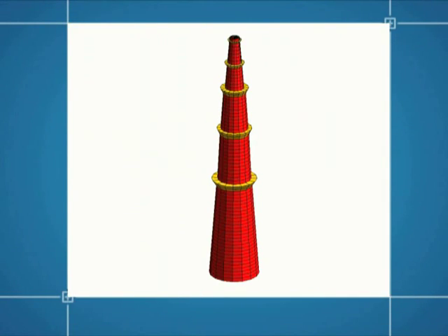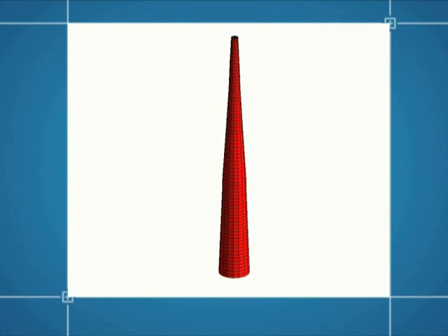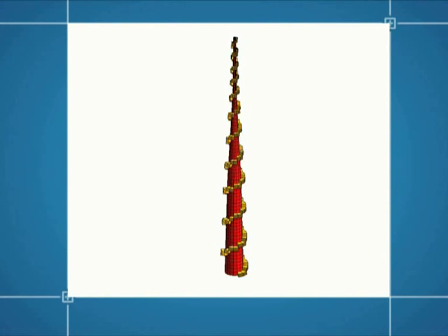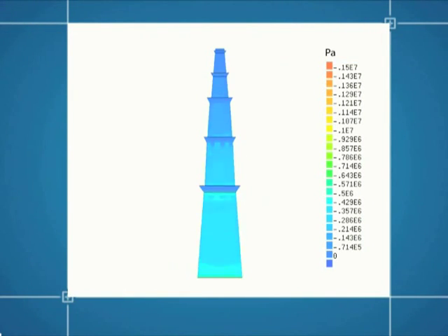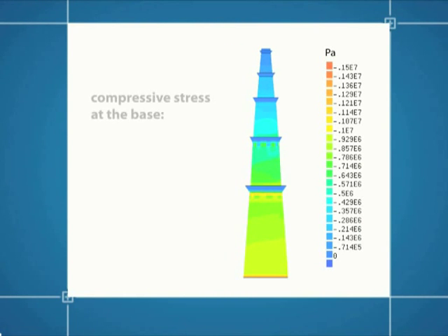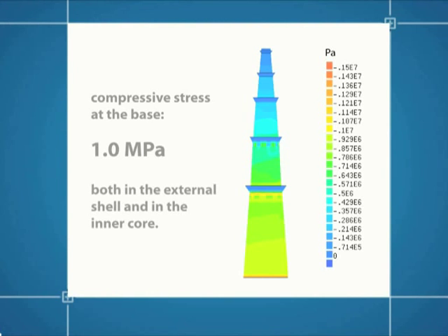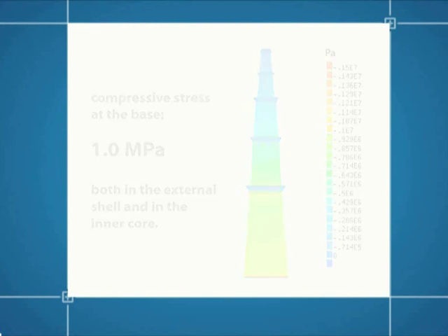The models considered to simulate the structural behaviour of the Qutub Minar take into account the different materials of the structure: the external 3-layered wall with the internal rubble masonry, the stairway, the inner core. Also, doors and openings can be taken into account. The actual weight of the structure was applied to the virtual model. This provided an indication of the present flow of forces inside the tower.